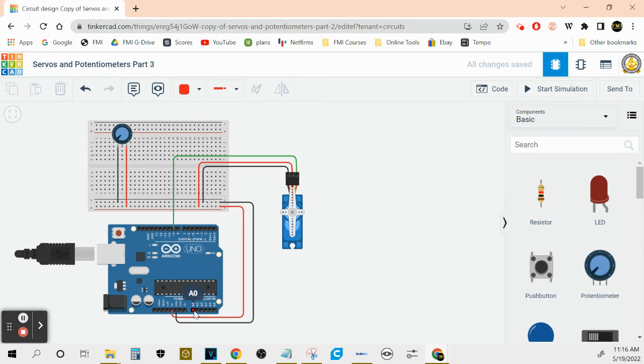That's going to go into the analog input way down here. So we got quite a path to go to. And I'm going to make that green eventually because I don't like red for the controller. Okay, stop here, there, and then let's make that green. Okay. All right, good. So when you wipe this, the information will go all the way down here. We'll go into here to A0, and then A0, we want the information to go into 9, and then that'll go right into our little servo.